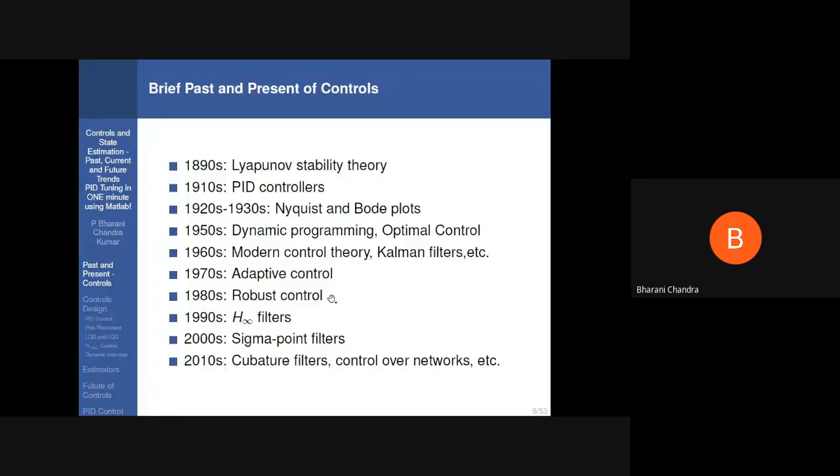So this robust control technique can deal with certain computational issues of adaptive control. But the problem with robust control is that the order of the controller could be very large. It could be as minimum as the order of the plant, or if more weights are included, then the order will be very high. Then the concept of model reduction can be used to reduce the total number of states of the controller and so on.